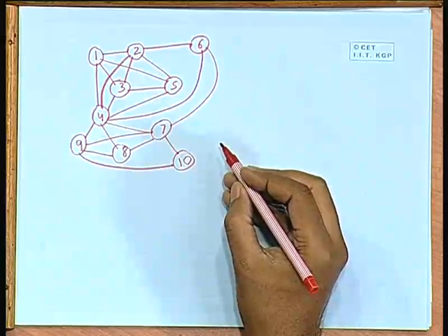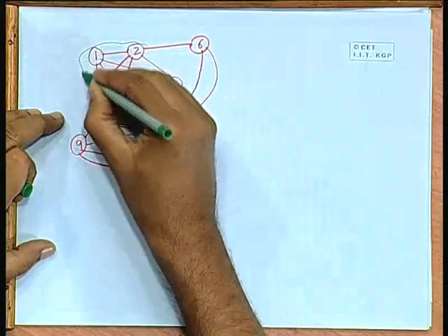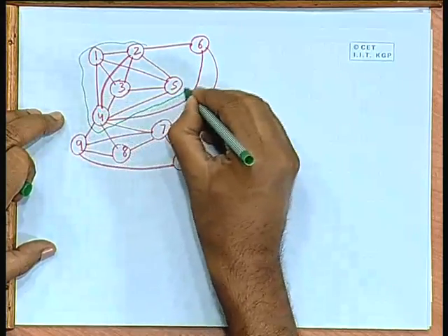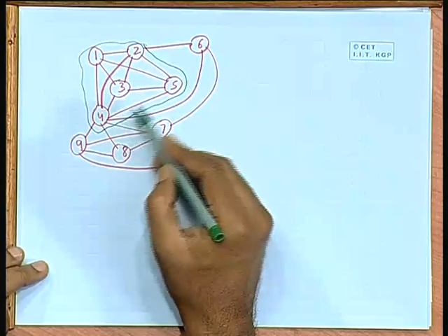Now, if you analyze the horizontal constraint graph, you will observe one thing, that in this graph there are certain maximal complete subgraph or cliques. For instance, this subgraph consists of nodes 1, 2, 3, 4 and 5. This is a clique. All these nodes are connected to all others.